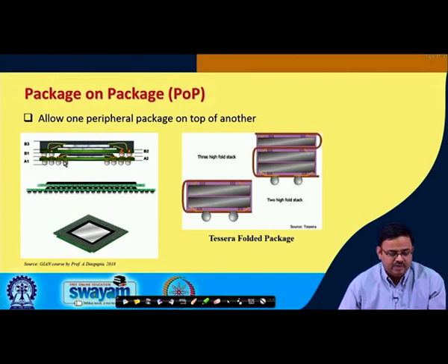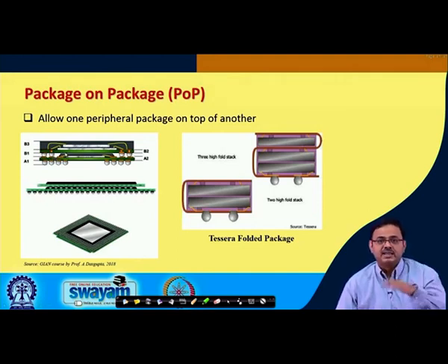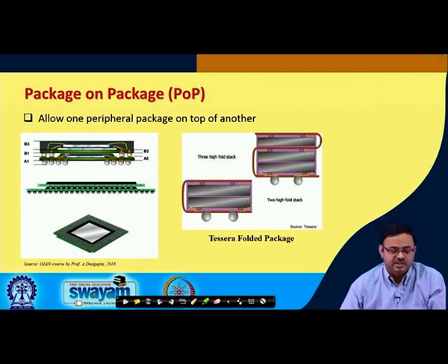So, therefore, outside the footprint of the silicon and the chip carrier and the molded plastic as shown in this picture, you have these solder pads on the top side of the substrate, and these solder pads are for the solder bumps for the package that come on top for the substrate of the upper package.